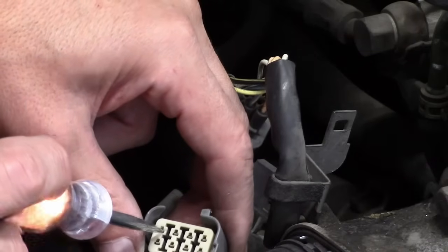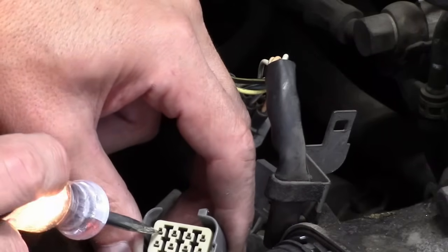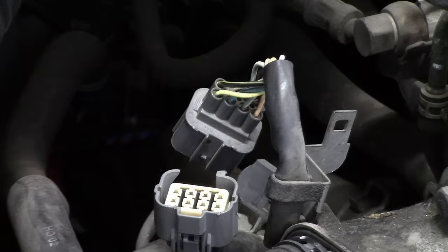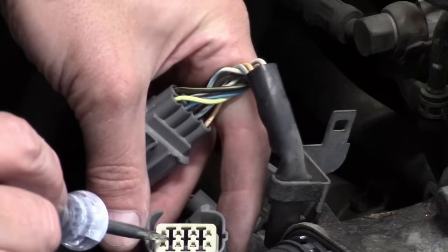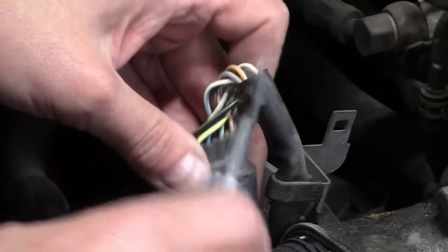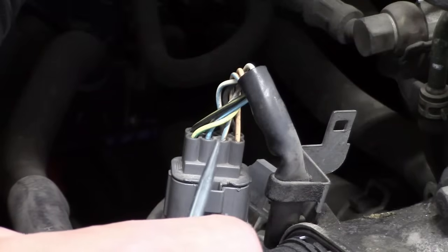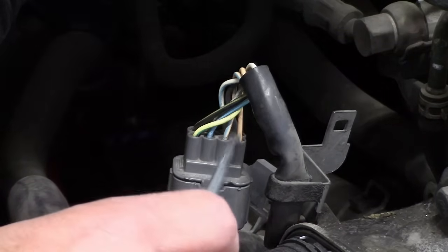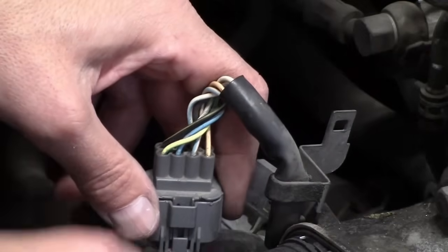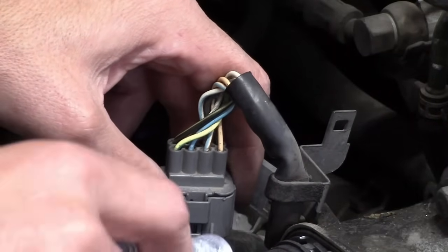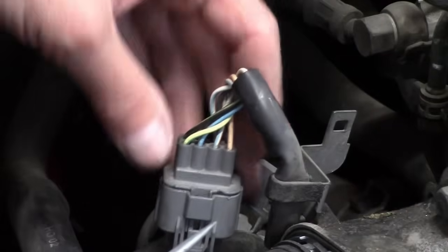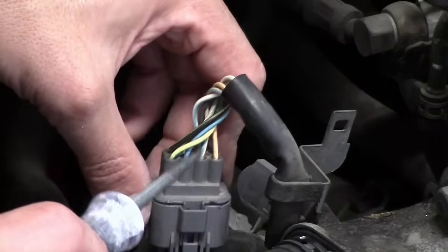Thought it was one of these corner ones right there. Found one 12-volt input, so that was at least some good news. That tells me right there this isn't likely to be a fuse issue or anything like that. I'm testing the fuse right there. So at that point, just to confirm, and again, I don't know the design of this, I'm just going on guesses right now, but I do believe we've got a crank sensor issue, or more likely, because this is a distributor engine, a cam sensor internal in the distributor. The distributor is driven by the camshaft, so very often the cam sensor is in the distributor.